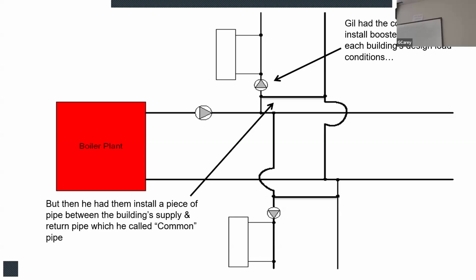Now, up until this point, that never happened, never existed. No one even knew to think about this. And he could see it. And he said, what I want to do is decouple these smaller little pumps that I'm going to size for that particular building's needs, its flow and load. And I still have my distribution, but I'll decouple it, so this guy is not kicking the daylights out of these smaller guys. So it's a simple little thing, but it's not, but it is.